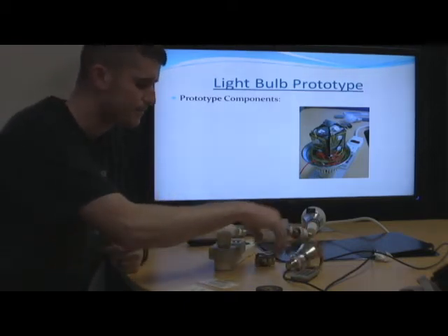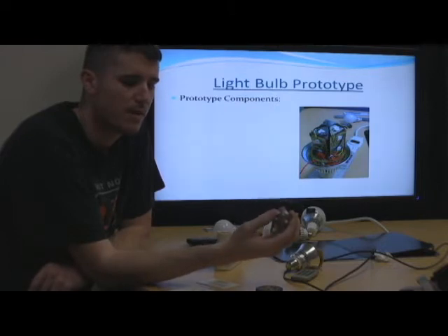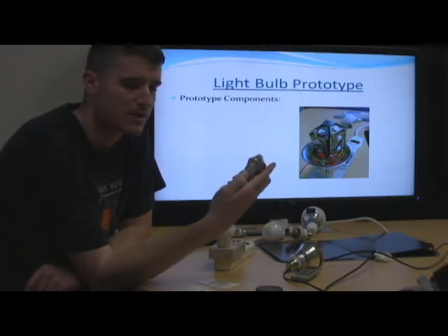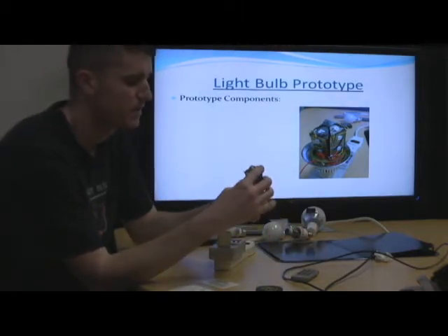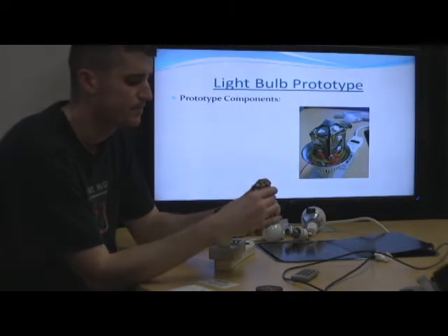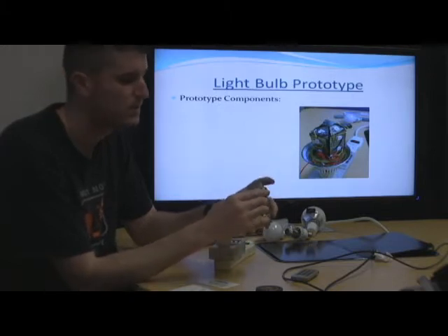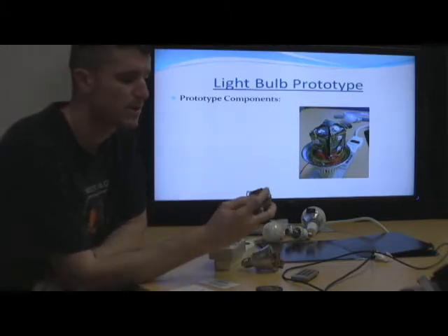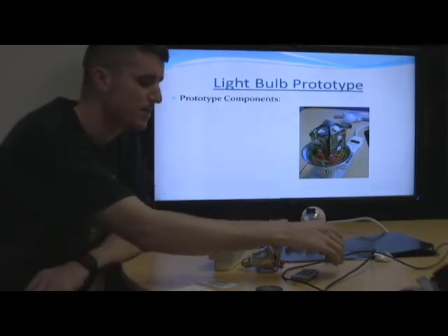The LED boards or driver, we first went with an obelisk, so we wanted these to be pushing out at 270 and up, and then these to be pushing out on the sides. What we ran into a problem with when we did it this way was that these bottom LEDs would get blocked by the case itself, so it wasn't really going out to 270, and these top ones were pushing out way too much energy up. So that is the problem with this design. We changed it later.